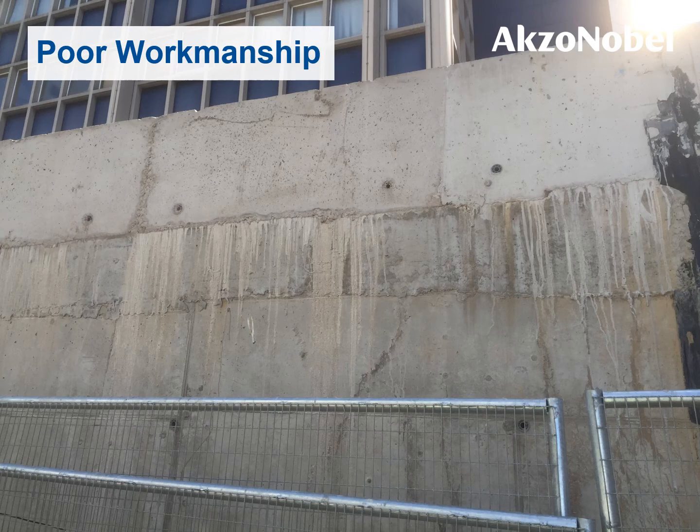The last example is from a high-value infrastructure project where we can immediately see a number of issues. Looking from the top, we note significant blowholes and tie holes which require sealing. We see poorly detailed day joints and leaking from the kicker. The infill beam appears to be of inferior quality and the substructure concrete is suffering from cracks. Unless promptly corrected, such deficiencies will, without doubt, diminish the anticipated service life of the building.